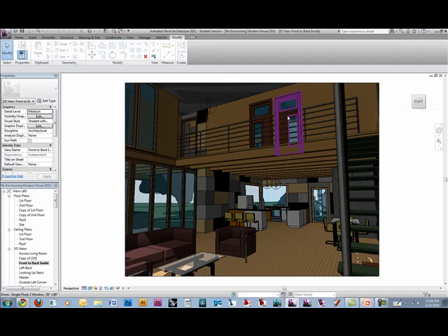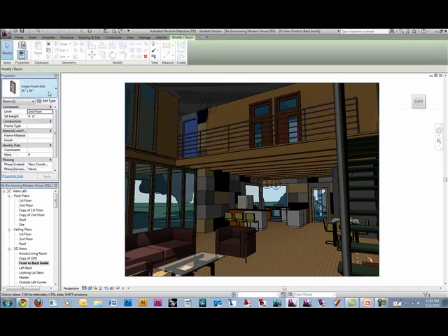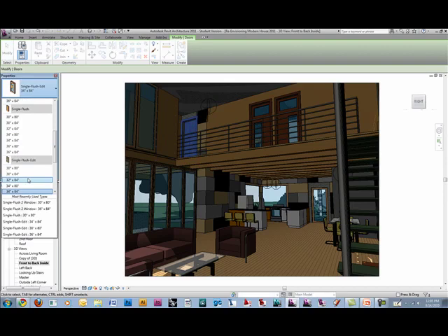And you could do stuff like add handles, because there's no handles on any doors in Revit. Because if you think about a rendering, say light bouncing off a chrome handle, it has a bunch of reflections, and sometimes it just wastes time in the render, so they don't do them. But you might want the doors to have doorknobs. If it's a little detail you're looking at, then you're going to want that doorknob in there. But if it's a huge building, you're not really worried about doorknobs being rendered. But it depends on the case, I suppose.